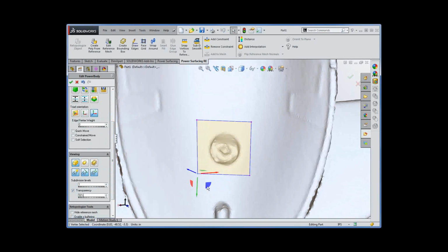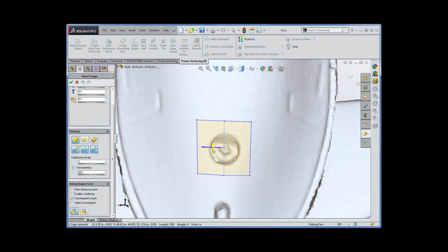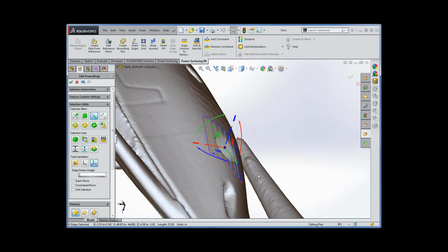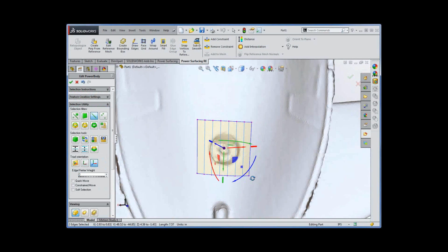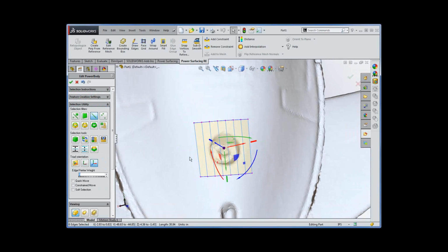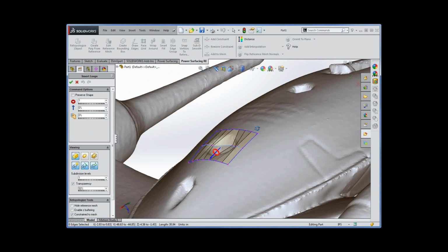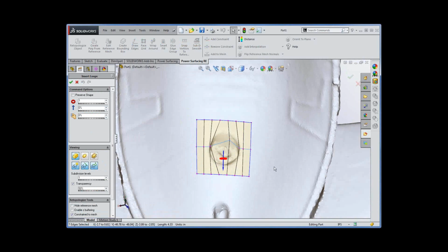And what we want is a nice smooth patch that's going to follow the contour. And the way we do that is we can subdivide, not subdivide, but we can add more edges, subdividing in one direction. And see here, because these are constrained, and we can tell they're constrained because they're magenta colored, they're following that contour. The problem, though, is as soon as we go the other direction, you can see they're going to snap to the closest surface they can find. Which is in the hole. Yeah, which is in the hole or on the edge or something. So there's something we can do for this.